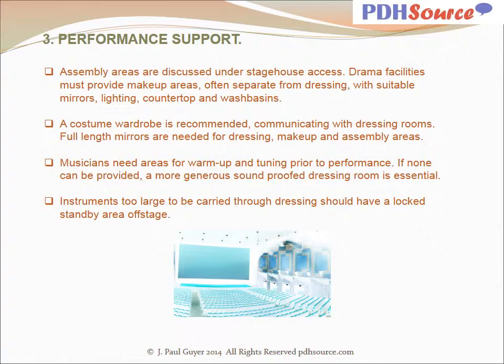Drama facilities must provide makeup areas, often separate from dressing, with suitable mirrors, lighting, countertop, and wash basins. A costume wardrobe is recommended, communicating with dressing rooms. Full-length mirrors are needed for dressing, makeup, and assembly areas. Musicians need areas for warm-up and tuning prior to performance. If none can be provided, a more generous soundproof dressing room is essential. Instruments too large to be carried through dressing should have a locked standby area offstage.